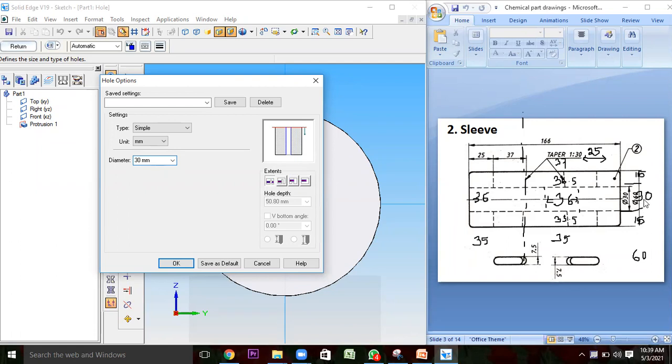But if you have multiple blocks kept in a single direction, in a vertical direction or in the x, y or z direction, and you select Through Next, then only a blind hole will be created. Then you have From-To Extent, where you choose from what point to what point you want to create the hole. Then you have Finite Extent, from one point to a depth, where you can also select what the depth should be.